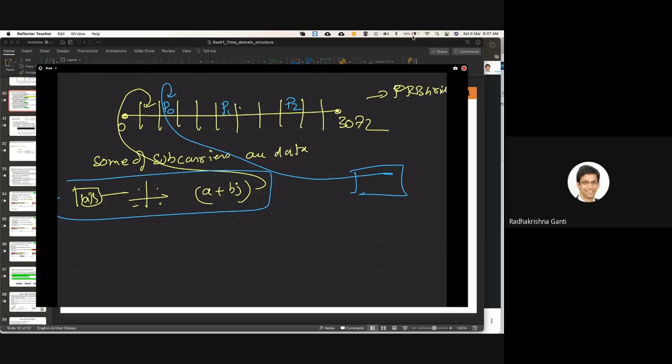And then what we do is, we have the 4096 FFT. Okay, so 4096 subcarriers are there. What we do is, we set all the subcarriers in this 4096 to 0 first. Everything is set to 0. Then we just map this whole array into this array.